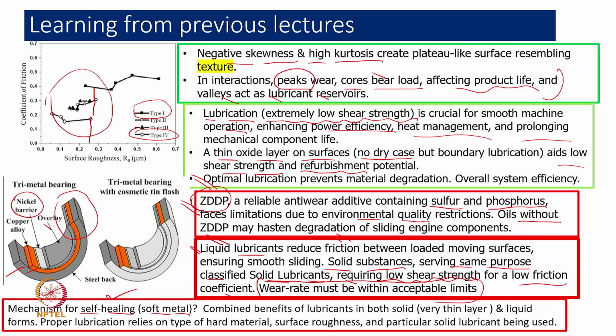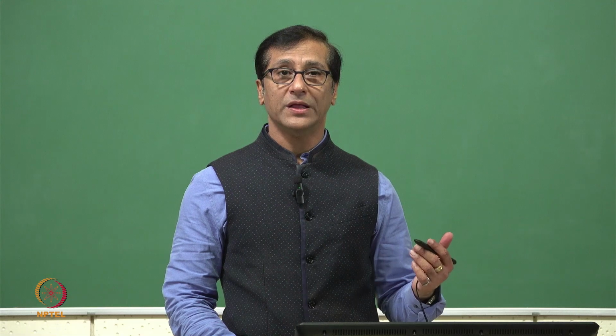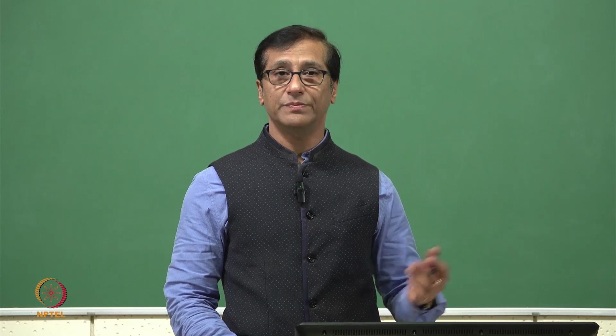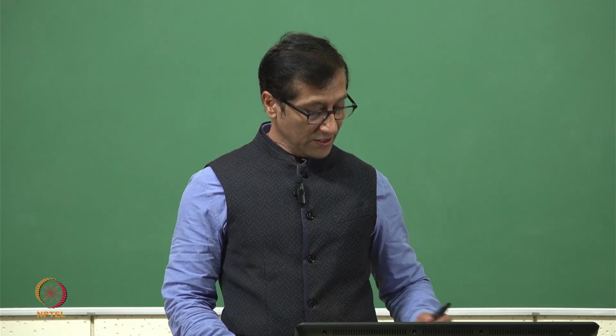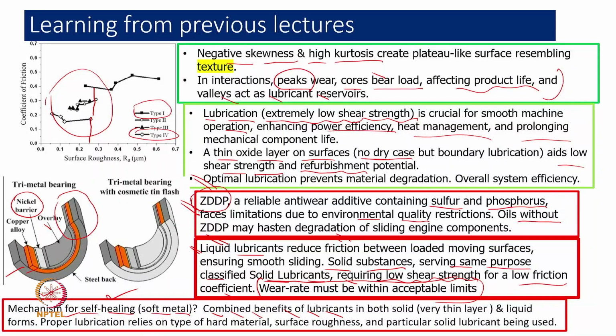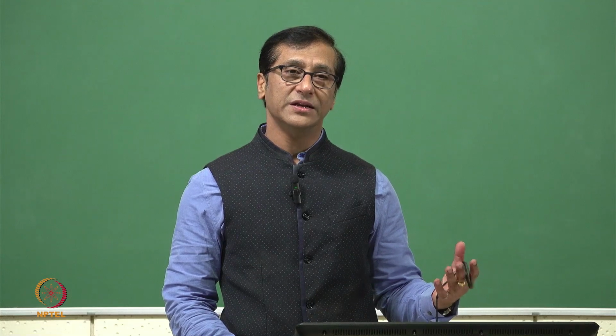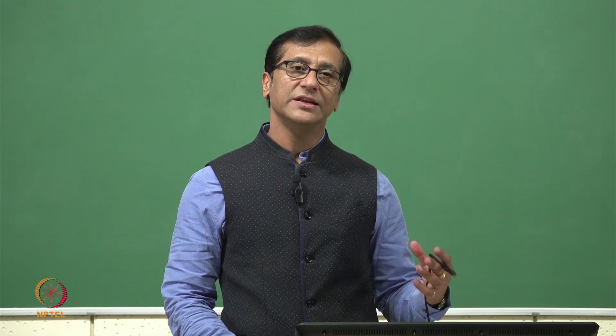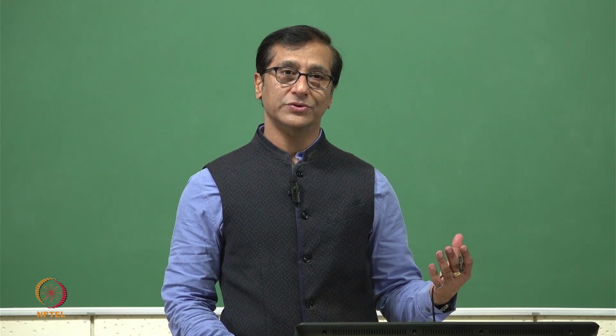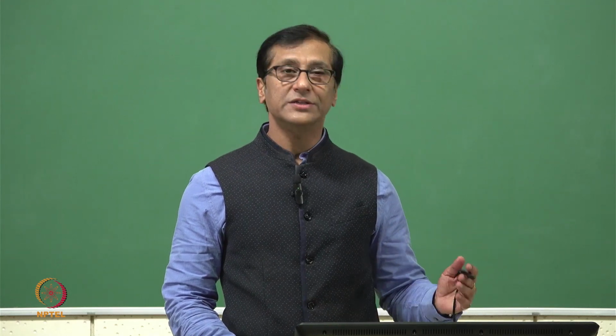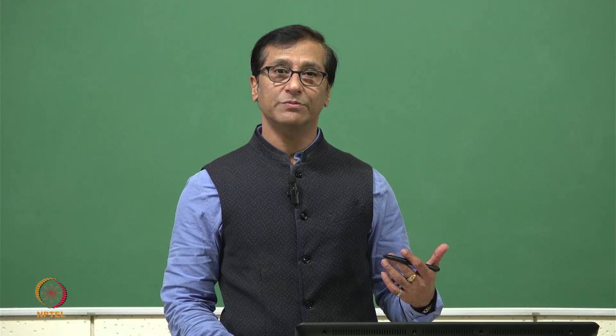Another point is that proper lubrication relies on a number of properties, as surface roughness was pointed out. This wear also depends on the hardness of the material, and it has often been realized that when the surfaces are hard, they don't deform plastically, and then they don't go ahead with junction growth either. So a thin lubricant layer will be sufficient for that purpose.